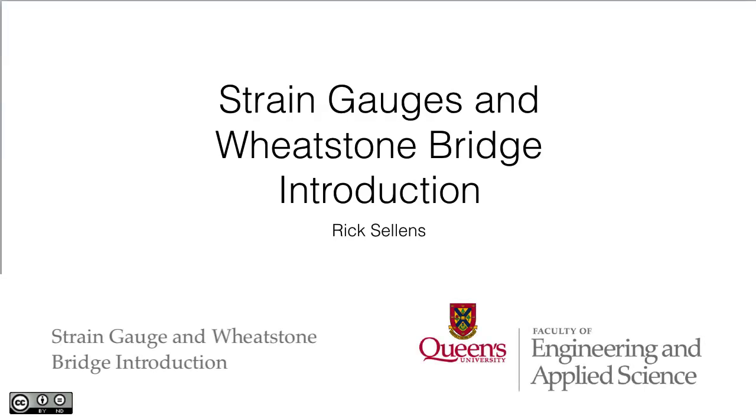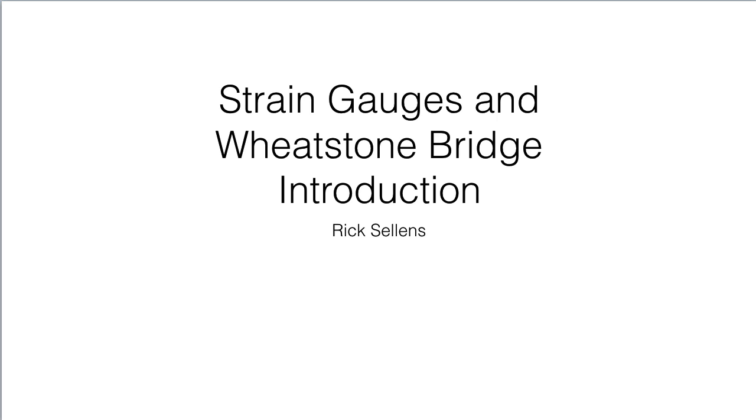Last week we found that strain gauges change the resistance a very small amount when they're stretched. So we'll need some kind of a system to allow us to detect that small change in resistance. And one of those approaches is the Wheatstone Bridge. So we'll do some more measurements with strain gauges later on, but this week I want to give you at least a brief introduction so you can start thinking about how we can process analog signals in order to get better measurements from them.